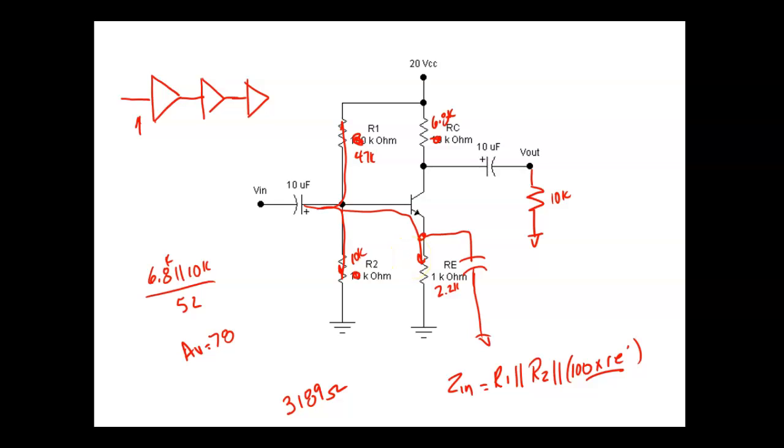So what we're going to do, if I come over here, let's say I have 10 volts, and let's say this is 5K, and I come up here and I can adjust that right there until this right here gets up, this goes to 5 volts. What does that tell me? That tells me that those two resistors are exactly equal to each other. You understand that? So as soon as that hits 5 volts, I know that my rheostat is 5K. I know it. So this is what we're going to do.